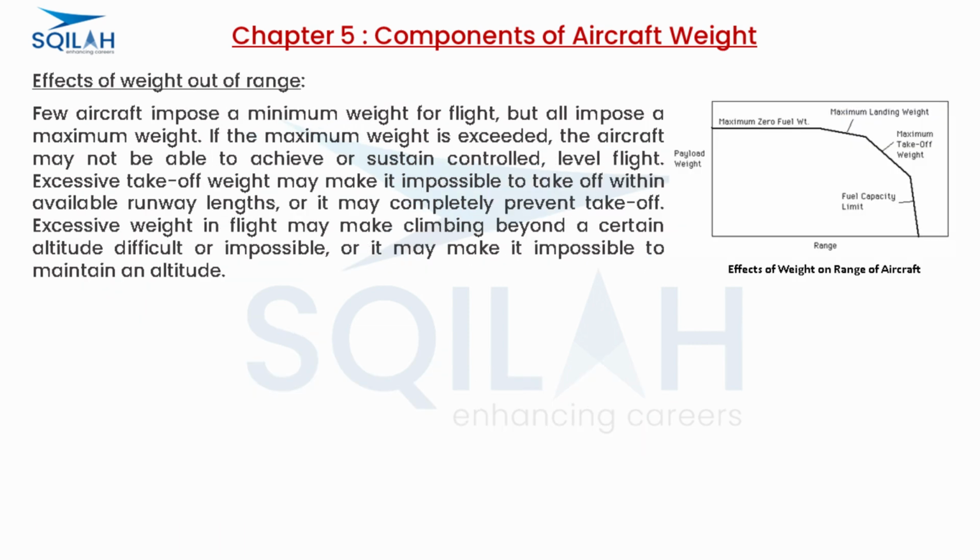Effects of weight out of range. Few aircraft impose a minimum weight for flight, but all impose a maximum weight. If the maximum weight is exceeded, the aircraft may not be able to achieve or sustain controlled, level flight. Excessive takeoff weight may make it impossible to take off within available runway lengths, or it may completely prevent takeoff. Excessive weight in flight may make climbing beyond a certain altitude difficult or impossible, or it may make it impossible to maintain an altitude.